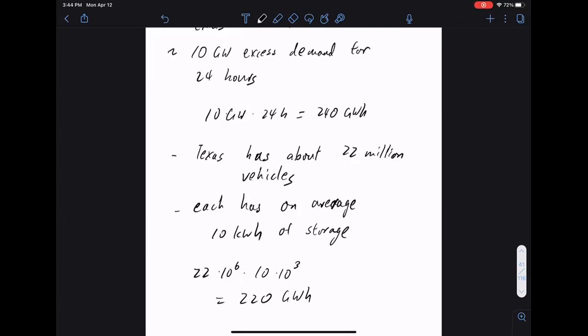So you look at Texas, you're 10 gigawatts short for those few days. Right now, if you want to add 10 gigawatts of load onto the grid, go for it. So when you need the power is really, really important, right? All a battery does is shift power around. But Texas was bad at that time because there was no generator. You couldn't turn a generator on. The week after the winter storm, Austin hit 75 degrees. So at that time, if you wanted 10 gigawatts of power, sure, the grid can supply it. So really it's a timing-wise issue. The ability to shift load around in time is quite powerful.